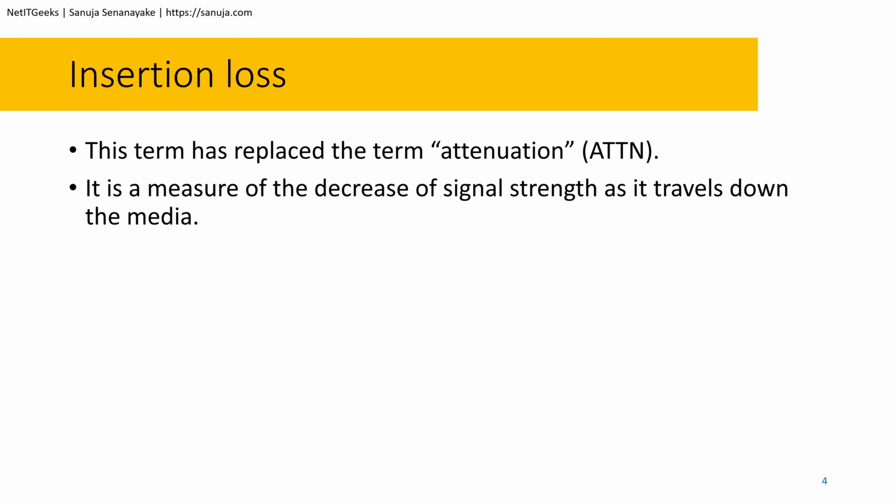Insertion loss is higher with higher temperatures, as higher temperatures increase the resistance of the conductors, resulting in more signal loss. So if you're in a warm, hot, or even humid environment, because humidity could potentially have an impact on the increased temperatures felt by the cable, that could cause a higher insertion loss.